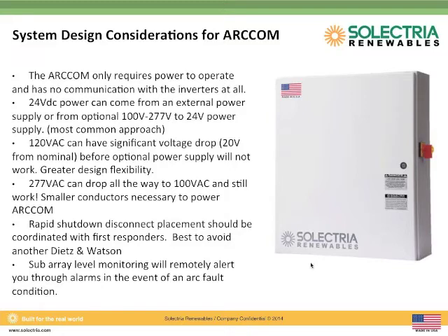And lastly, I can't stress enough that the subarray level monitoring is your best means of detecting if you've got an arc situation out in the field. I see a lot of people compromising their ability to keep their systems up and running and understand exactly what is going on as far as the health of their system, whether there's an arc fault, whether it's underproducing or otherwise, by not having some of the tools that have been made relatively available from Selectria, from other inverter manufacturers, and through our third-party data acquisition providers. Data is the best way for us to be able to help troubleshoot any issues that you may have, and also help you determine how to manage your asset to its fullest potential.